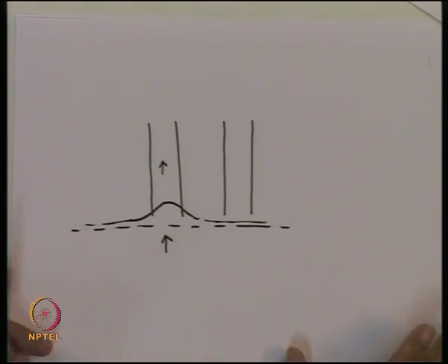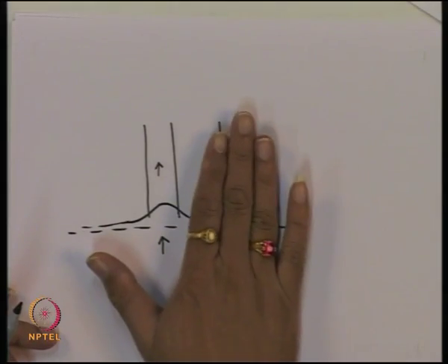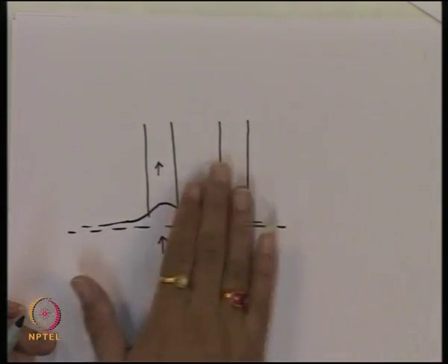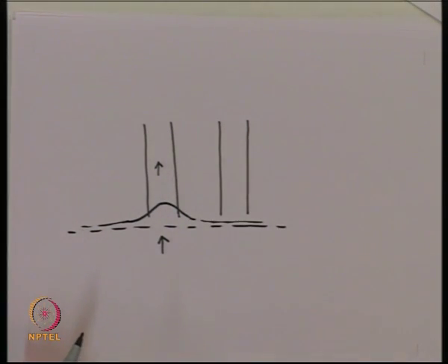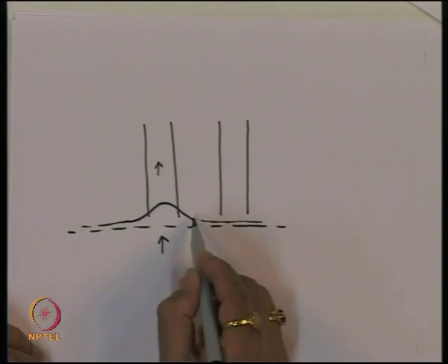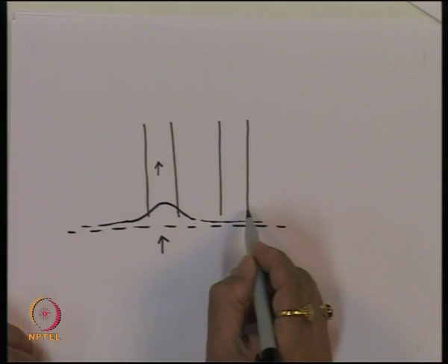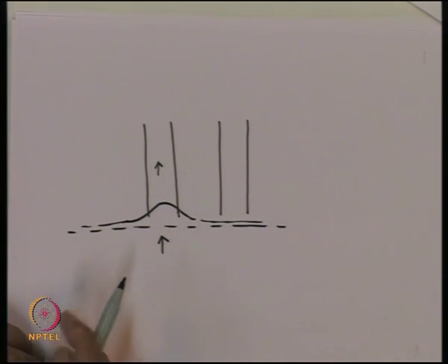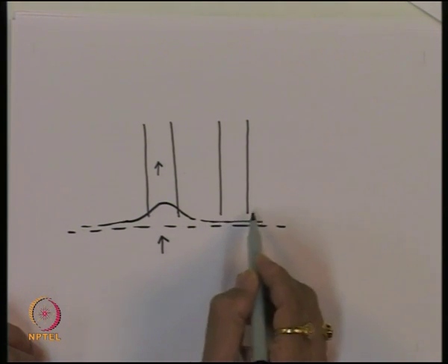Now let us say we have another identical channel waveguide and we bring it close to this waveguide without touching each other, just in the proximity of each other. As soon as you bring this waveguide close, this field, which is extending theoretically up to infinity, is now intercepted by this. So obviously this distribution cannot remain like this because now the boundary conditions are changed.